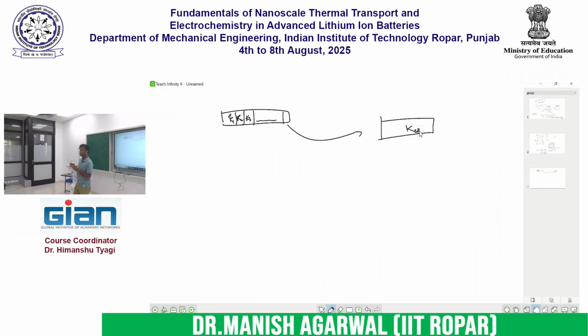So this is homogenization. If I simply define it, it is converting a domain which is actually heterogeneous into a homogeneous domain. That is what homogenization is. It can be in a structural problem, a thermal problem, or a fluid problem, but this is what homogenization means in any field. Okay. So do you know how to derive the K effective?